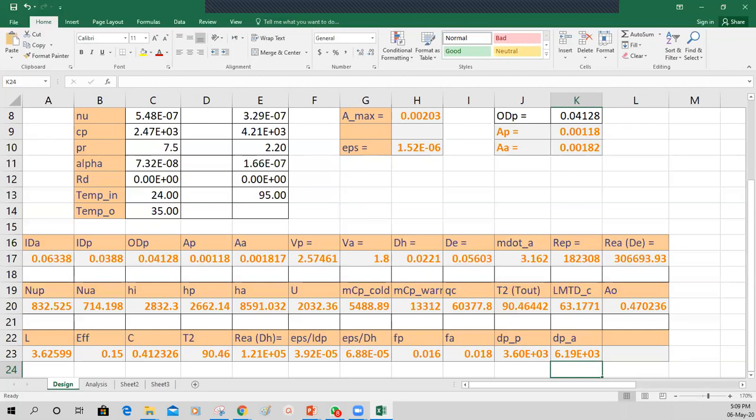So there is a limiting point after which the increase in cost is very steep. Somewhere there we can put our limit: up to this pressure it is okay, but beyond that the cost increases more. So in the book, they decided that 70 kilopascal is the pressure limiting criteria.